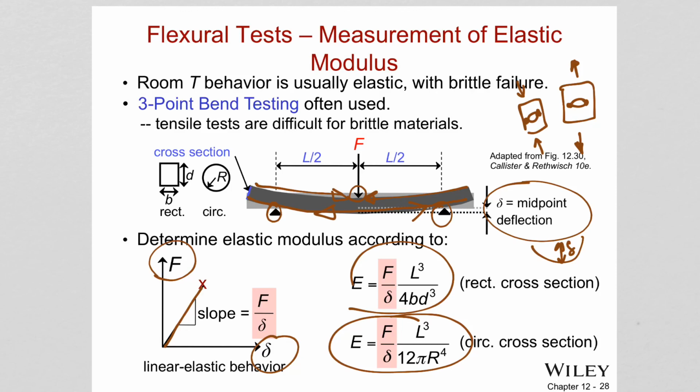Think about bending, different types of shapes are different, right? You need to apply different forces. When you're trying to bend a circular cross-section, it's going to be different than some rectangular or square cross-section. Therefore, this shape factor comes in the calculation of the bending stiffness, and therefore this factor has to be also included in the calculations, in the equations.